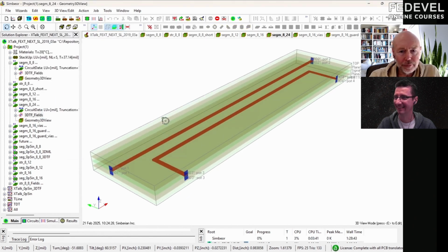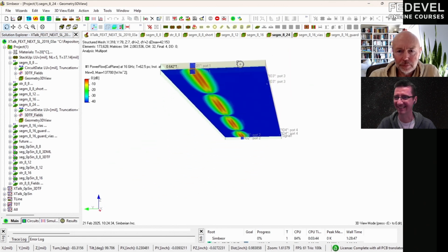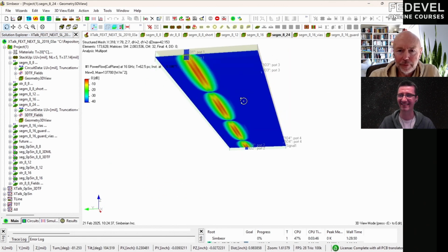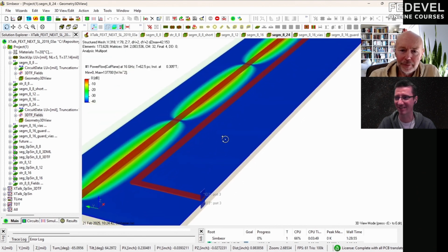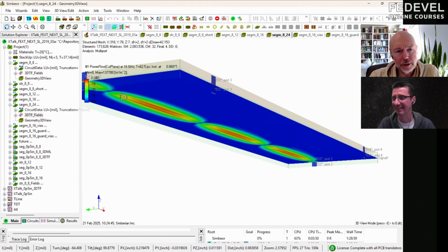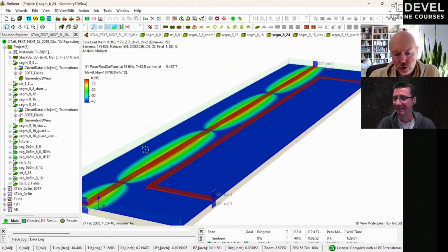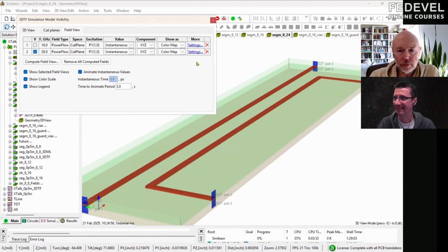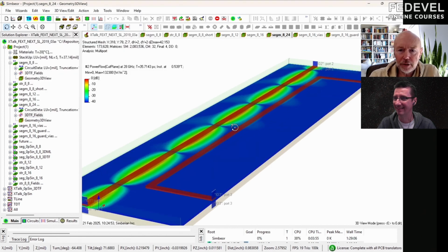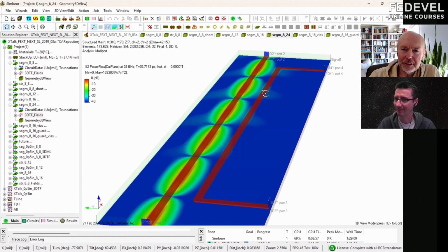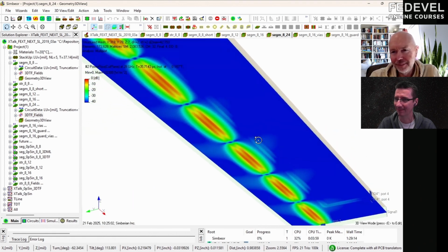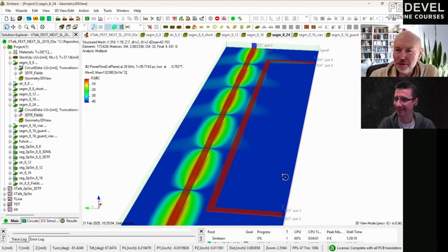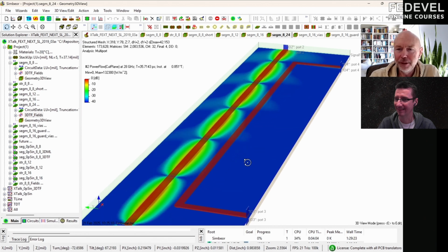Okay, fields. Oh, well, this is cool. You can nicely see the fields. They are not as big as the space between them is, so they are not touching, in those sense, at the level of minus 40. So let's take a look at 28 gigahertz. But at 28 gigahertz, you can see that it starts gaining far-end crosstalk from those leaky waves. And at that spot, it's difficult now. If you even move it further apart, you'll still get it.